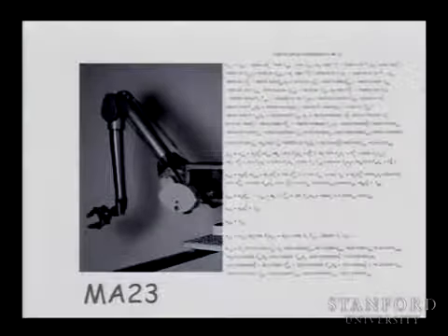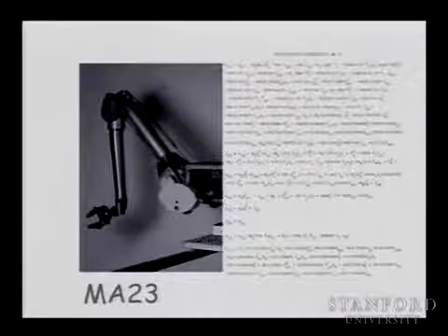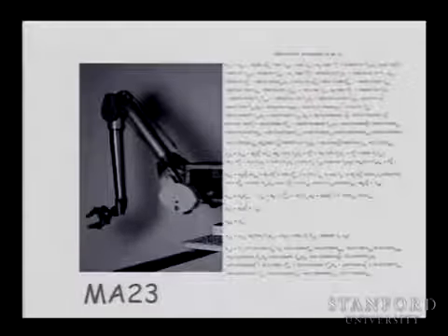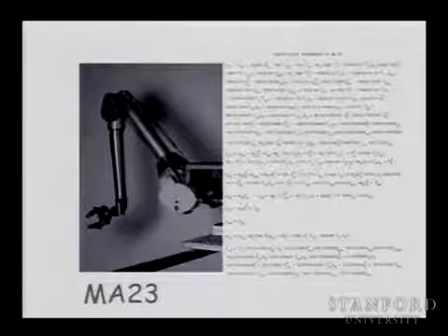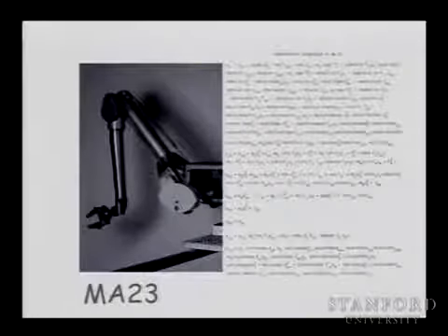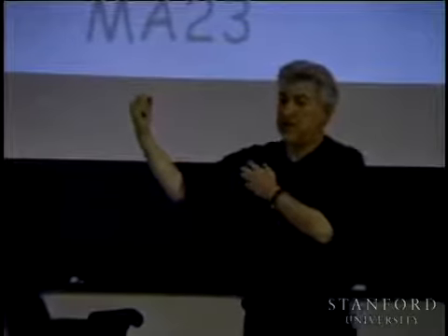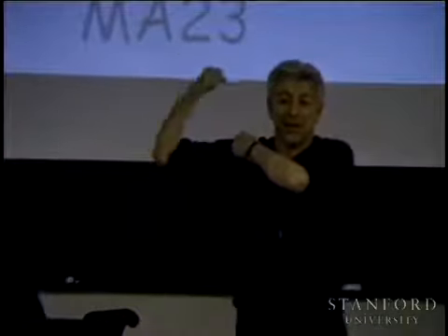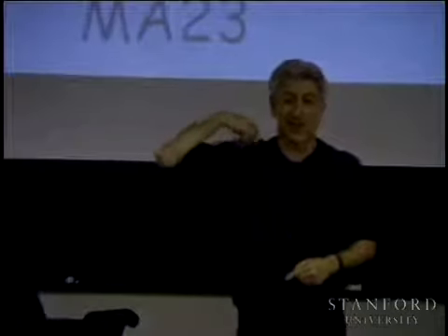So you see on the right here, this is the robot, and here you have some of the descriptions. You cannot see anything probably, but you have all the descriptions of, for instance, what is the inertia viewed from the first joint when you move. So this inertia is changing as you move. Imagine I'm considering the inertia about this axis. If I'm deploying the whole arm, the inertia will increase. If I'm putting the arm like this, I will have smaller inertia about this axis.